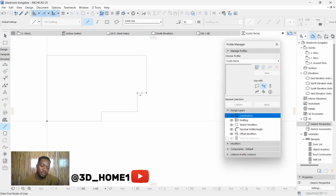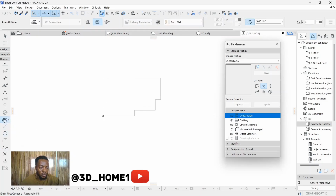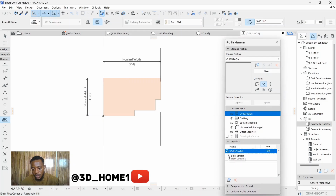So now we need to fill in this space. This thing looks too simple. Okay, I don't need something simple, Sha. Now we need to fill in this space, and we do that by clicking on fill tool. Once you click on fill tool, bring your cursor here, hold down your spacebar button and click inside. Then under modify width stretch, top stretch, that one needs to be checked.